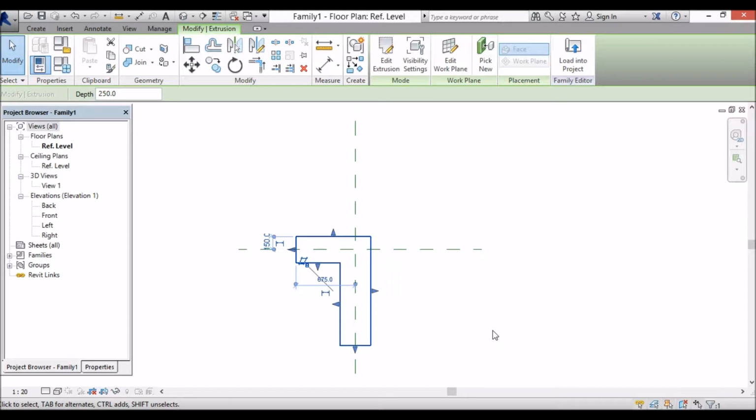So the next thing we need to do is to position the element, which we won't need to do for the base because that's going to be positioned on the bottom of everything, so that's fine, and to apply a height parameter to the shape. We haven't actually dimensioned the height yet or created a parameter for that, so I'll do that next. When you are creating the length, width and depth parameters, you could create the height parameter there, but you won't apply it until we get to this next step that I'm about to show you.